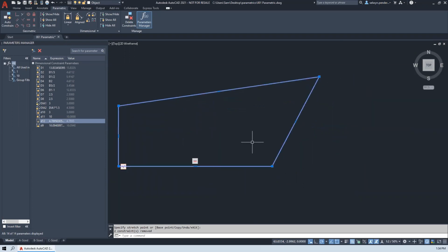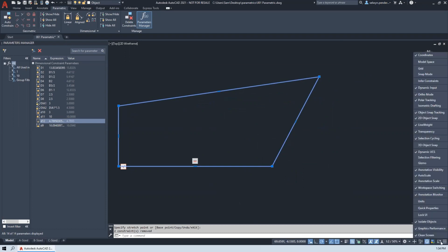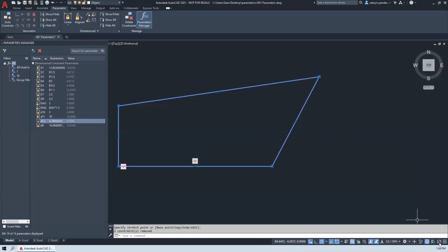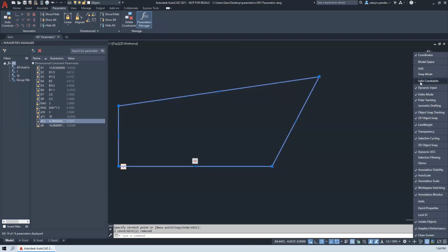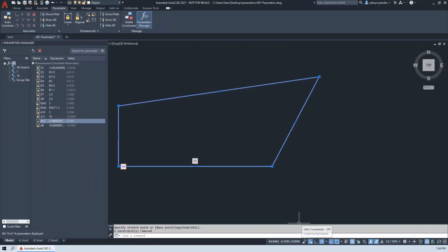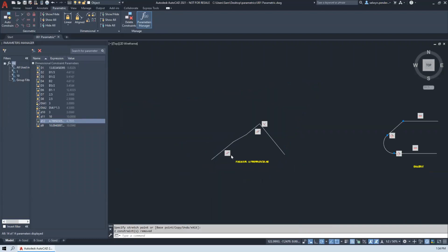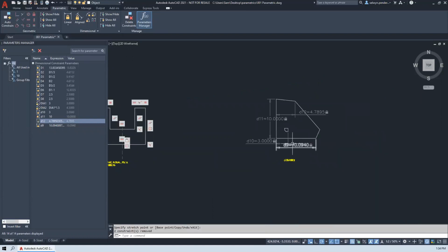Okay. So we're going to have a look at constraint settings at the moment. But before we do that, there's an icon that we can have down here called Infer Constraints. So up here, we right click on the little hamburger type thing down here, click on Infer Constraints, and that will bring up this window here. You'll see the shape of the object here. And if we hover over an object here, we'll see there's a constraint. You can see that little symbol that looks similar to this one here. That merely signifies there's a constraint applied to that object.